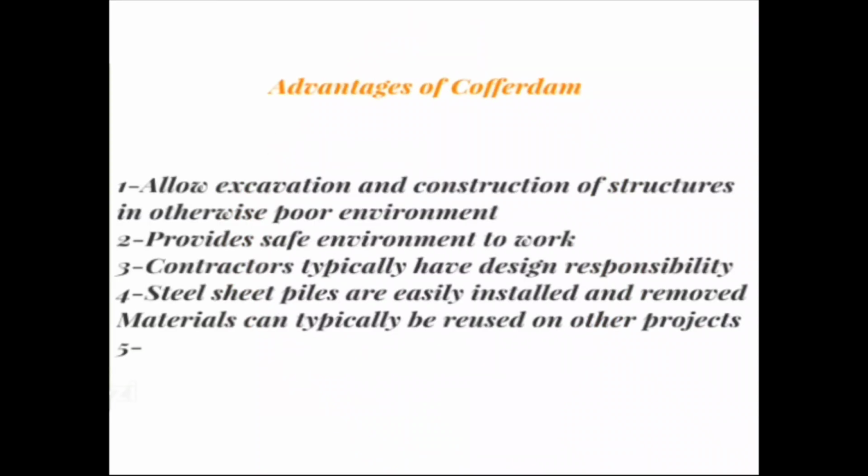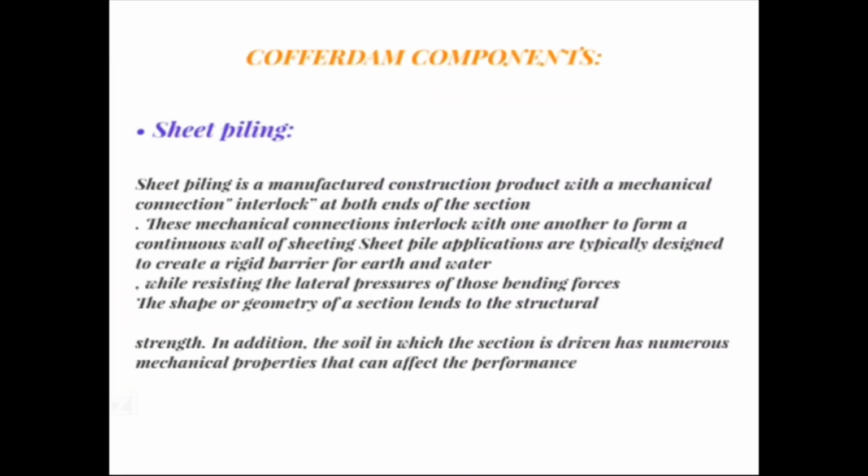Advantages of cofferdams. Number 1. It allows excavation and construction of a structure in an otherwise poor environment. Number 2. Provides a safe environment to work. Number 3. Constructors typically have design responsibility. Number 4. Steel sheet piles are easily installed and removed. And the last one is that the materials can typically be reused on other projects.